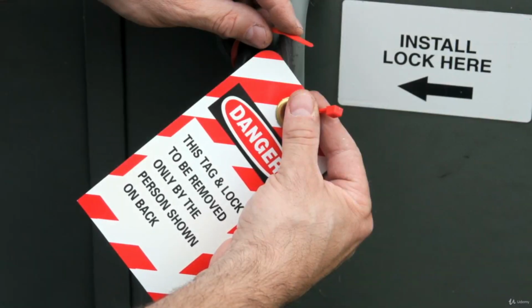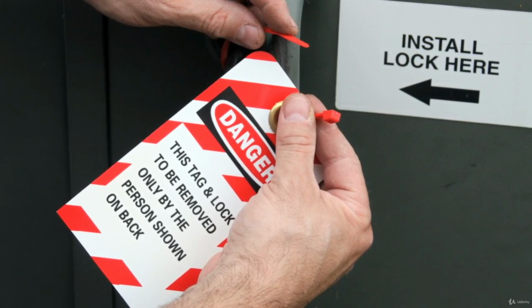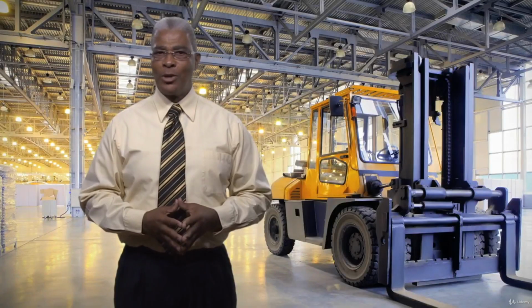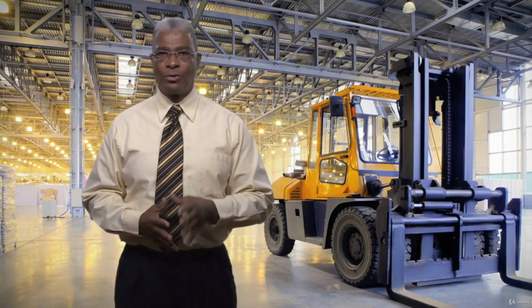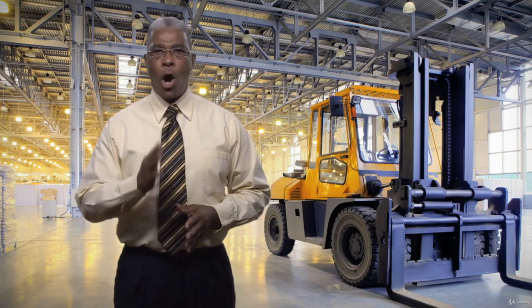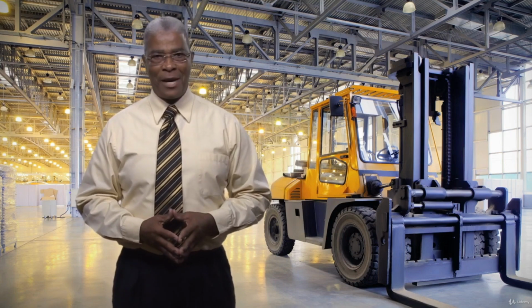They also must be substantial. They must prevent removal without excessive force or unusual techniques, such as bolt cutters or cutting tools, and must be substantial enough to prevent inadvertent or accidental removal. They must be non-reusable type, attachable by hand, self-locking, non-releasing with a minimum unlocking strength of 50 pounds, and similar in general design and basic characteristics to being at least equivalent to a one-piece, all-environment tolerant nylon cable tie. And locks and tags must be identifiable.